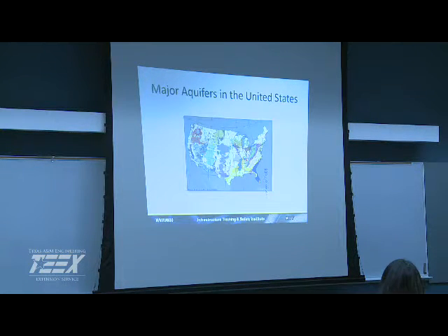But so then you get into other areas, and you've got to put your well so deep, because even though you've got a big aquifer, you can't get the water to the well, and that's why a lot of times you'll go to another source, because it's easier to pull it off of the lake than it is to have that many wells out there to put them so deep, because now it's more energy cost, stuff like that.